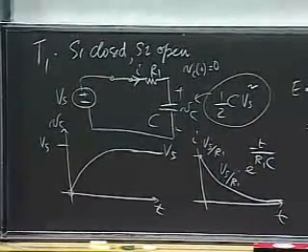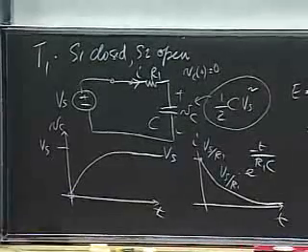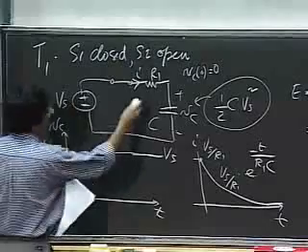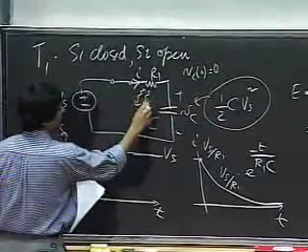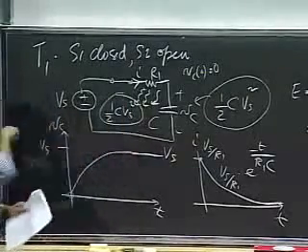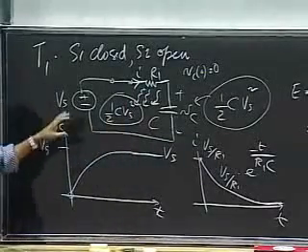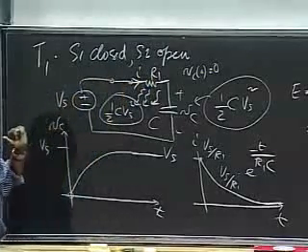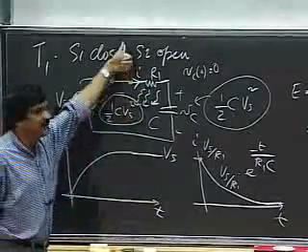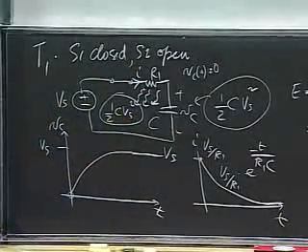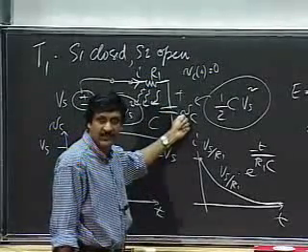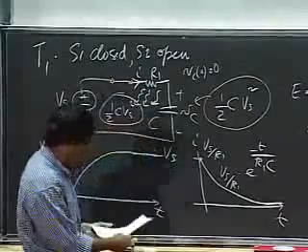The resistor, exactly. So the resistor has walloped half the energy. Let me just show it to you. So dissipated: half C Vs squared. It's pretty interesting. It's a pretty simple result. If T1 is very large compared to the time constant, then half the energy is on the capacitor, and half of it has been burned by R1. This energy hasn't been burned, it is simply stored by the capacitor.